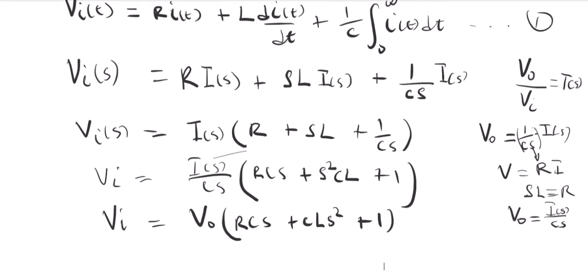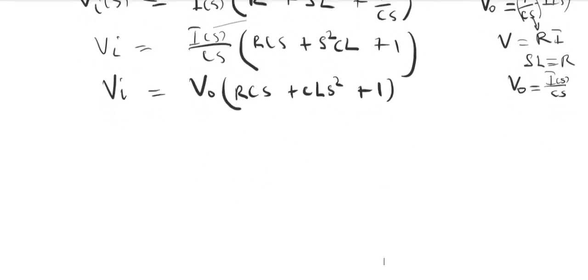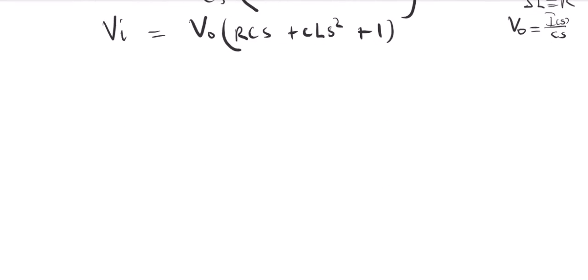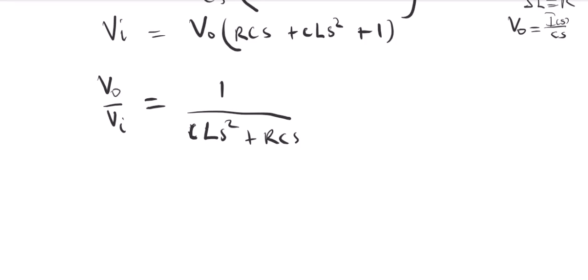Having done this, I'm going to express the output over the input, which is equal to 1 over, let's start with CL now, the highest order, CL S squared plus RCS plus 1.